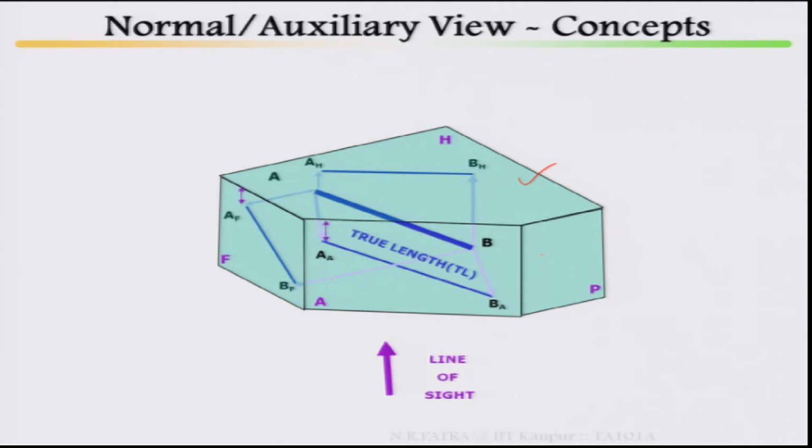If you look at the distance from this hinge line to this point, it is the same as from this hinge line to that point, because I am taking the auxiliary view of the top view line, so the opposite view is the front view. That means from the hinge line this distance and this distance are the same. Similarly, the distance from this hinge line to the front view will be the same. So this is all about how distance comes into the picture in 3 dimensions.